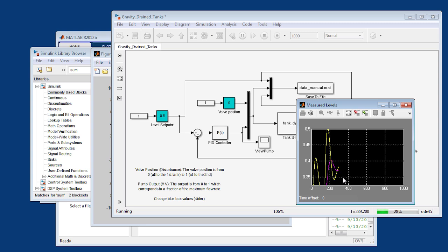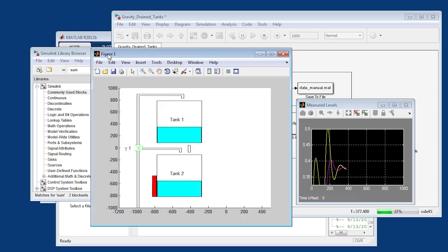It might level out somewhere right in this area. Okay, so with a proportional only controller, there's often offset, but you can tune it for applications like pressure control or sometimes a level control as well.